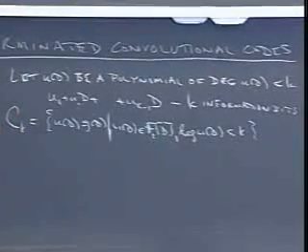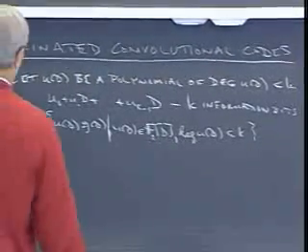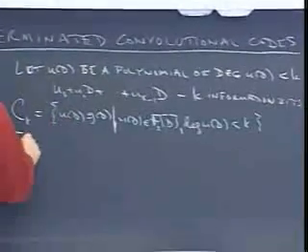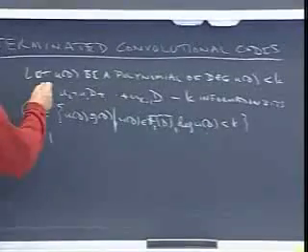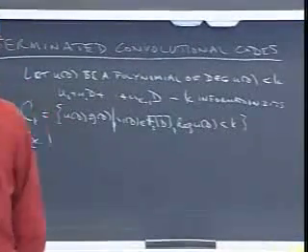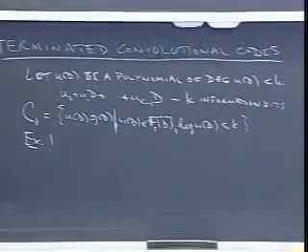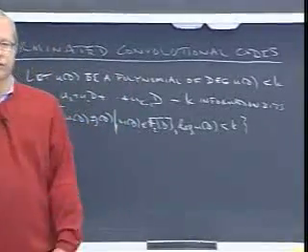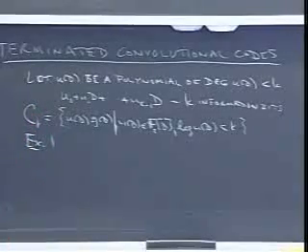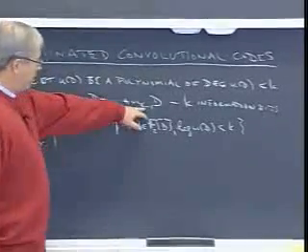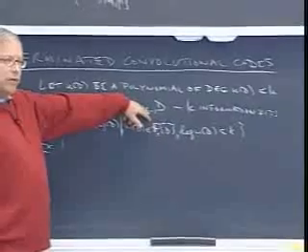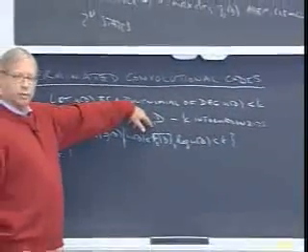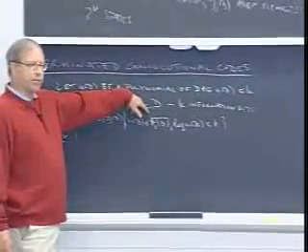Okay, so we ask what that code is going to be. Let's take some simple examples. Turns out when we terminate codes, we always choose polynomial encoders, so that the code will naturally collapse back to the 0 state. How long? Nu time units after the input stops coming in. The outputs will be all 0 at that point and forevermore.